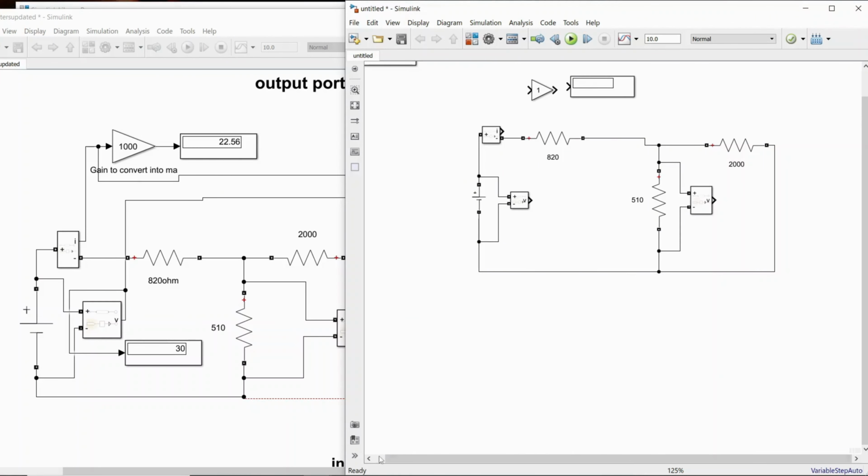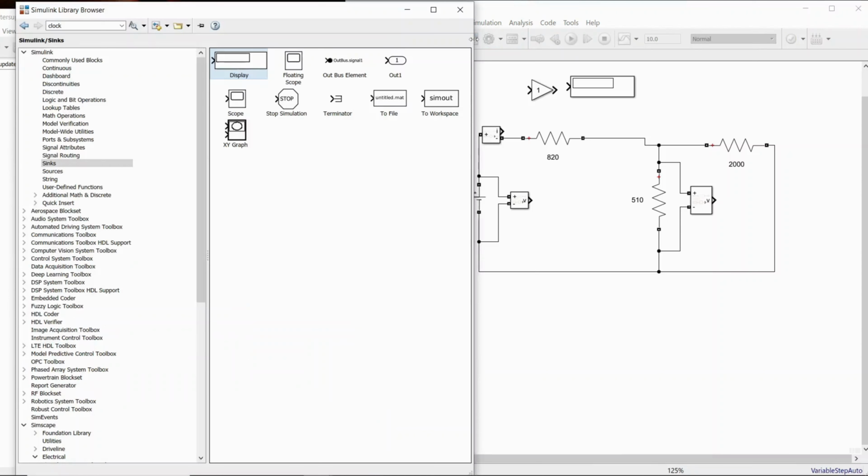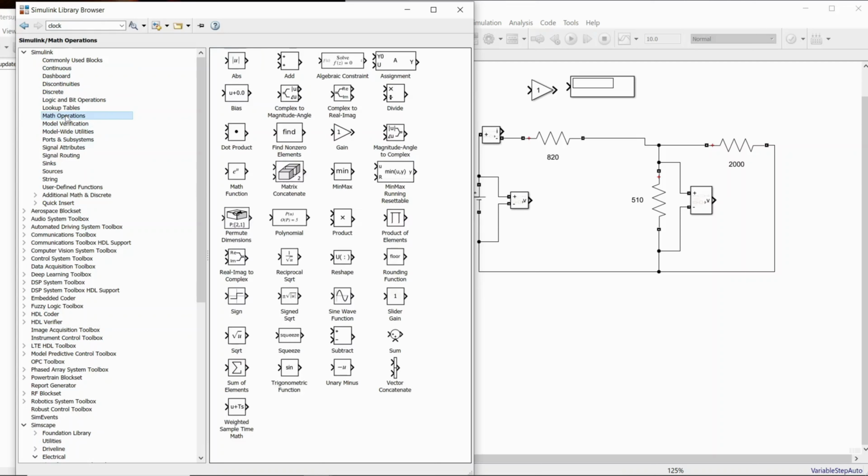Okay, so where is the multiplier we need to identify. You can check it by clicking on the library again. So this is the multiplier, and division is a mathematical operation. Click on the mathematical operation. You have to have a numerator and denominator. You can see here where the multiplier is, multiply and divide. Here you have this option, just click it and bring it out.